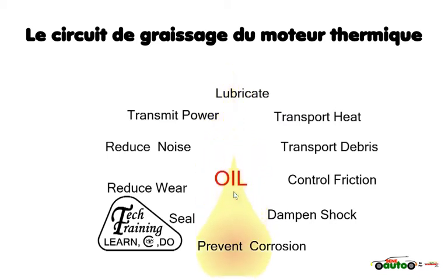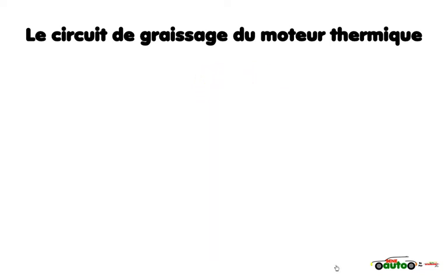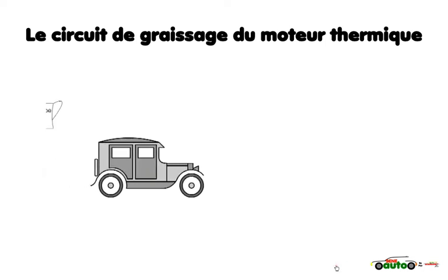Modern engines use low viscosity synthetic oil as the clearances in the bearing have been reduced and less energy is required to pump. The oil must fulfill other tasks, such as hydraulic oil for the cam timing advance system and hydraulic tappets. The grade and viscosity must be suitable for the engine design and operating conditions.